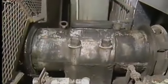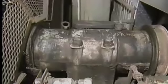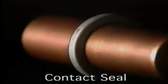Most sliding surface bearings use shaft seals to keep the lubricant in the bearing and dirt and grit out. Two common types of shaft seals are contact seals and labyrinth seals. Contact seals are generally fixed to the bearing housing. They rub against the shaft as it rotates. Contact seals are made of soft materials, such as rubber or felt, so that they will not damage the shaft.